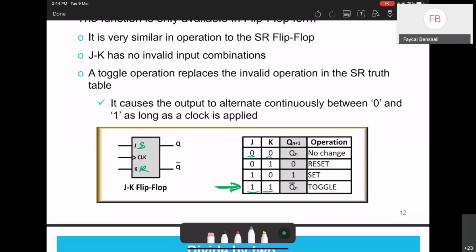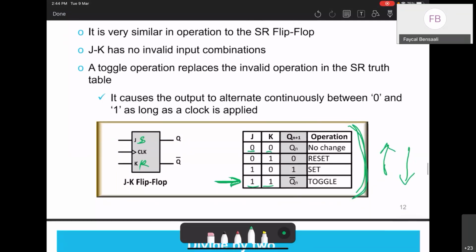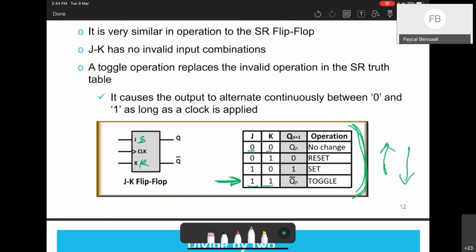So we can have the three possibilities. Let's say we work with rising edges. So this table, we will consider it for rising edges. If we work with falling edges, then this table, we will consider it for falling edges. And that's it. I think it's very simple. It's the same as what we did with the D flip-flop.